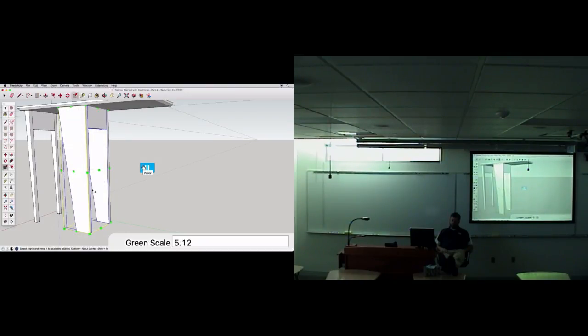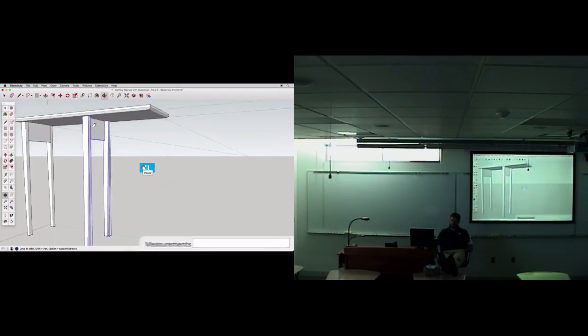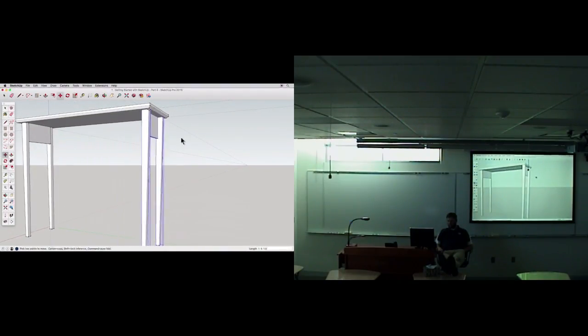Undo any scale effects you have created. Select all 3 parts and scale along this center grip until you see -1, which the tool will also snap to, and click to finish. Now move the assembly into place using the corner of the table and your guidelines for placement.